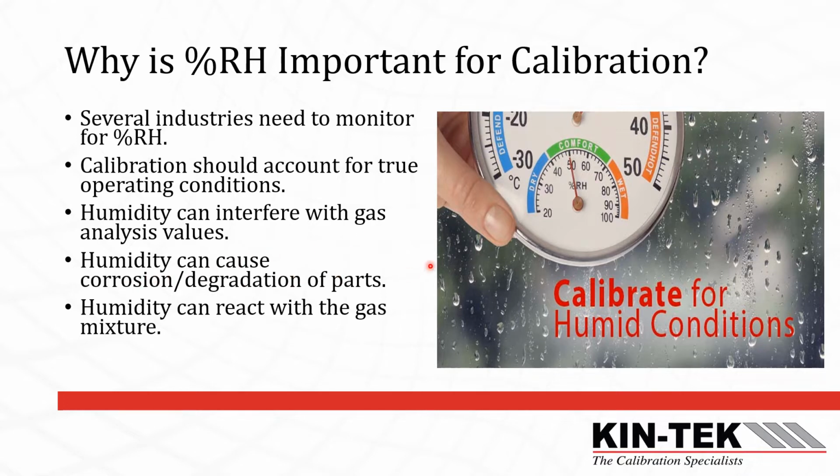Humidity also causes corrosion and degradation of parts, and humidity can react with the gas mixture. So for those reasons, if you're working with detectors or monitoring devices that you need to calibrate, and they're being used in humid environments, you want to mimic the same true operating conditions when you do your calibration.